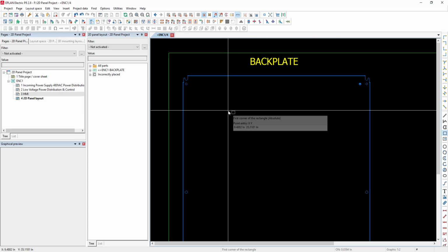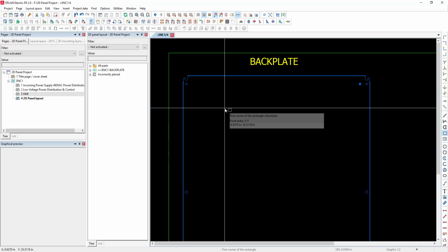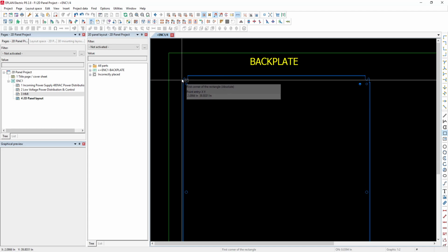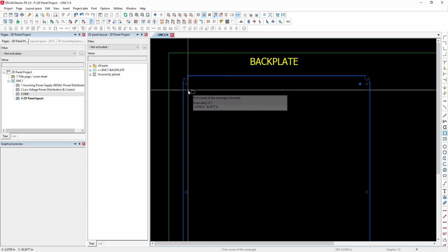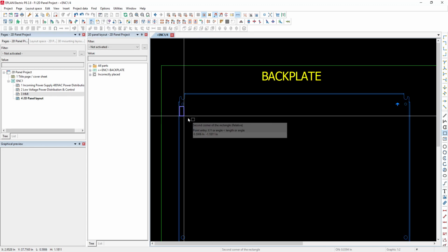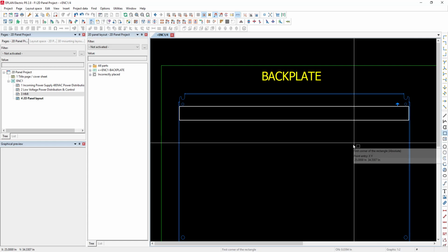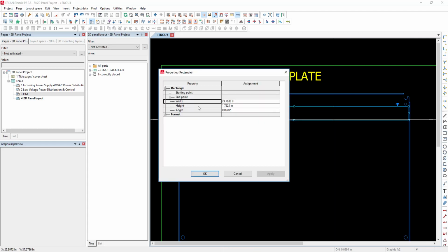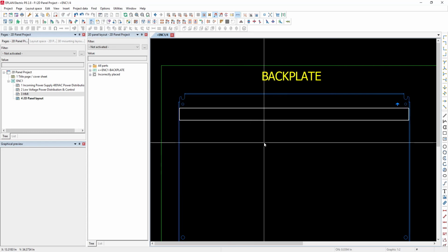This environment came out as of 1.7, which is almost like 10 years ago. So you can understand that development wise, this is not something they were really focusing on. That's why, again, Pro panel is the way to go. In this particular case, just drawing a rectangle. If you want to be more explicit on the particular size that you want to use for your wire duct, you'd have to type it in. So I want a 1.5 inch by whatever, 29. That's fine. Leave that as is.